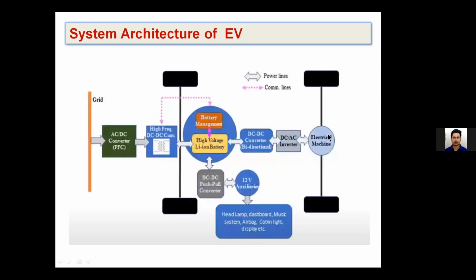And here, as we mentioned, let us assume we are using an induction motor, which is basically an AC motor. It requires some AC supply, but your battery is DC in nature. So again, here we need to convert from DC to AC. So how to convert? One possibility is we can convert DC to DC, I mean, we can boost the voltage, and this DC voltage can be converted to AC by using an inverter. It may be a three-phase or single-phase inverter.